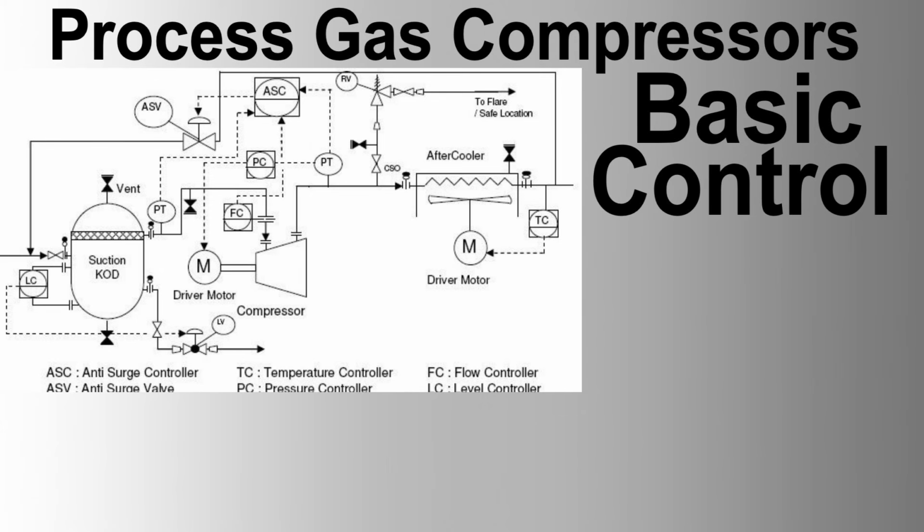A variable frequency drive, VFD-driven process gas compressor, is a crucial component in oil and gas upstream processing facilities. These compressors help in managing gas from low pressure, LP, and medium pressure, MP stages to high pressure, HP stages, facilitating gas injection and export. Here's a detailed process description of such a system.